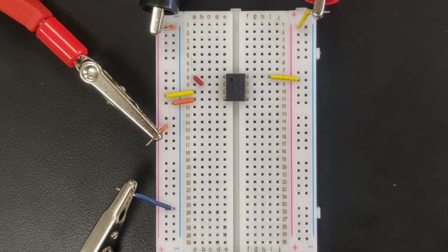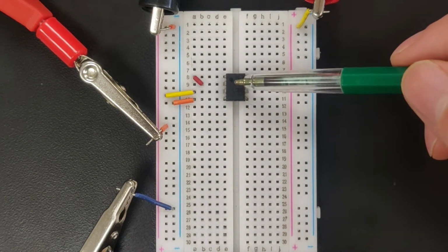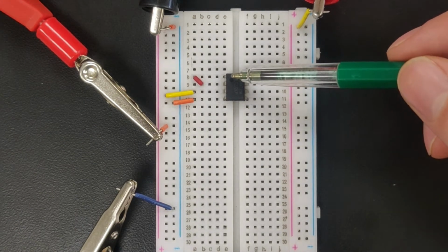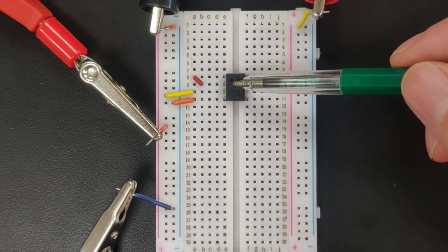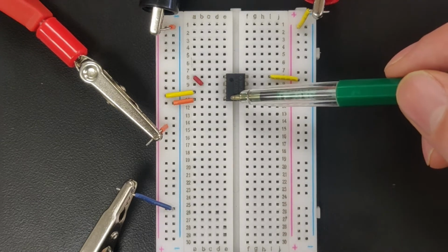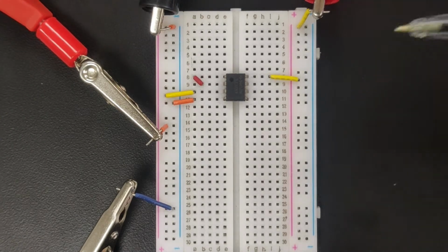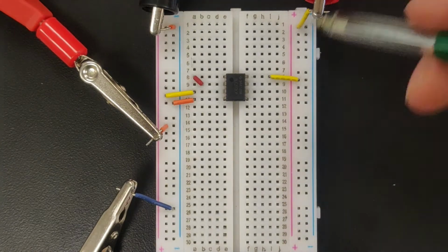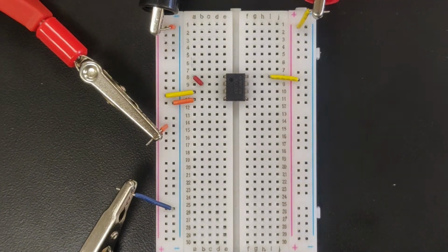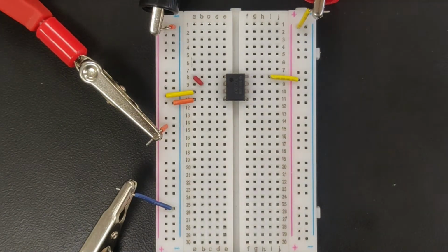All right, so I have built the voltage follower circuit for part A. Let's go through it. Right in the middle is our op amp, and our top left pin is our Vout. Underneath it is the negative Vin, the positive Vin, our ground, and our VDD pin, which is where we will be getting our DC voltage supply from our power supply. The other three pins are another op amp if we wish to use it, but we're not going to. We're only going to be using these five pins for all the circuits.